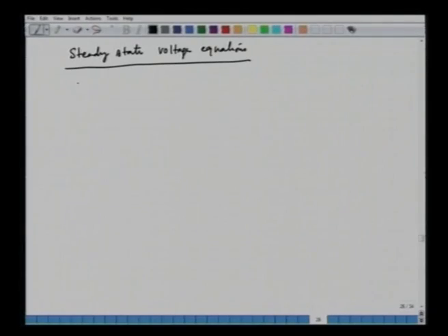Of course, in the transient condition, in addition to the field and the armature, we also have the damper currents, which will have some dynamics or which will delay the torque response. So, in the steady state condition, damper currents do not exist. So, what we have here is the following. We do not have any P terms here. The flux linkages are constant. So, we do not have any P terms, and all the quantities are the DC quantities, because we are talking about the rotor reference frame.